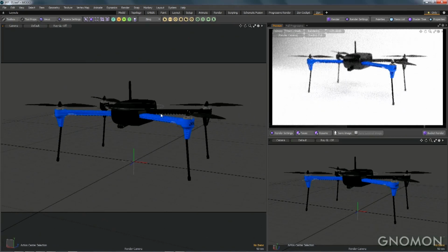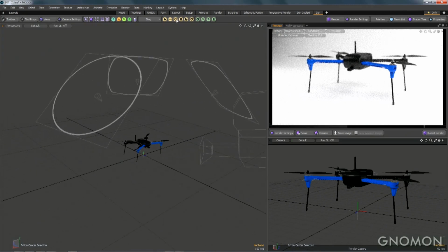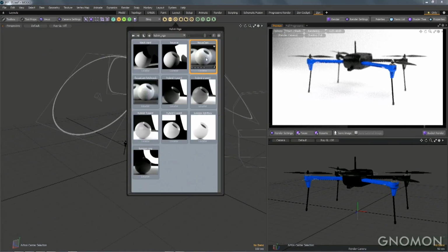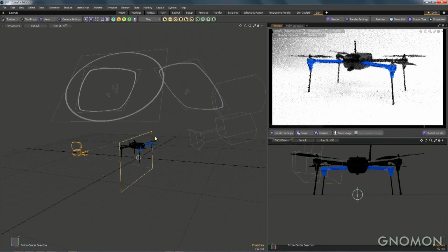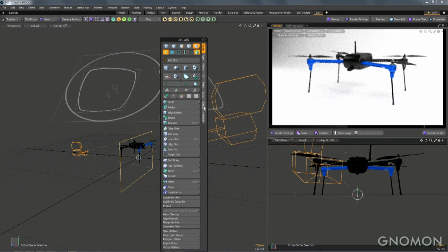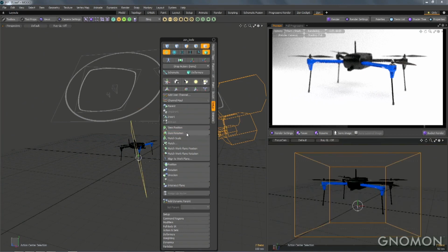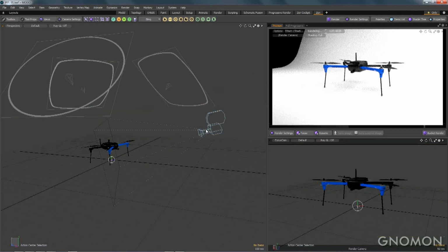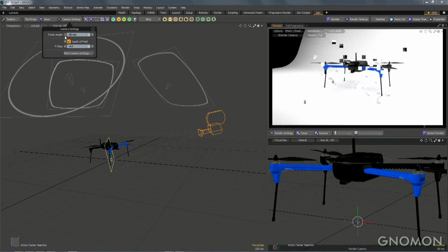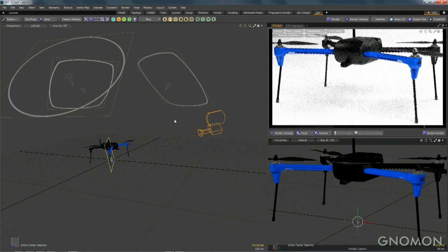So we have a couple of camera rigs built into Kelvin that are pretty awesome. One of them is called Focus Cam. I use it primarily for still shots. Actually, probably for 90% of my still shots, I use this camera. I'm going to select both cameras, and in Zen, once again, like every tool that we need is built into the Zen toolbar. I'm going to match item position and rotation so that our cameras are matching again, and jump in and change the focal length of this camera, again, just to set that up to what I want it to be to start, and start to frame this shot.